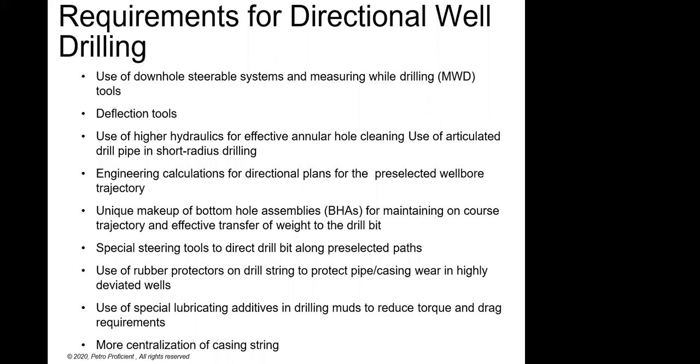The BHA should transfer the weight, and this is a very typical issue in highly deviated wells, where the weight is not transferred to the bit. And as you know, in a lot of cases, you need to have weight on bit to drill. So this is highly important.